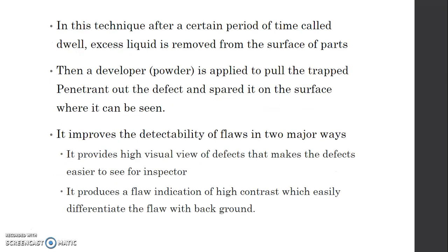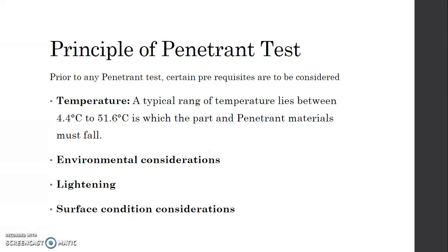Normally we call it dwell time when we apply the penetrant on the particular component. We have to wait a certain time for the liquid to penetrate into the cracks or defects. Normally it is called dwell time. Then we apply developers to pull the penetrant out of the defects, right? We will see this with the diagrams.